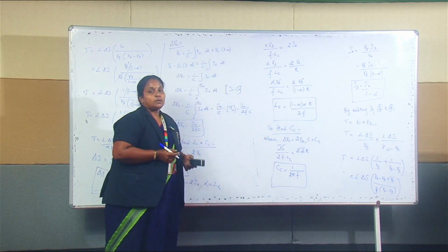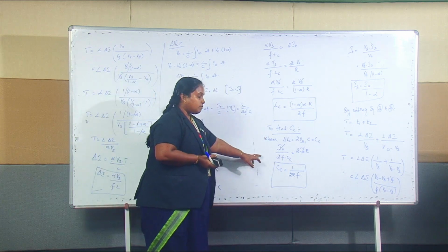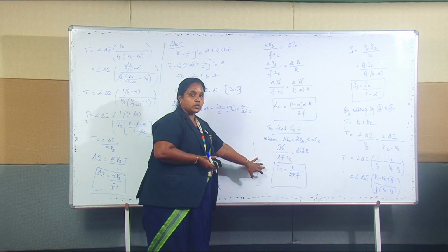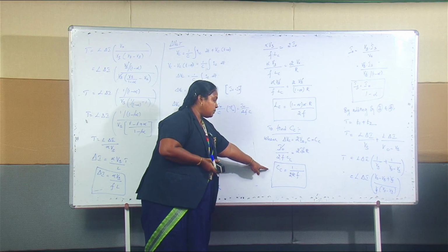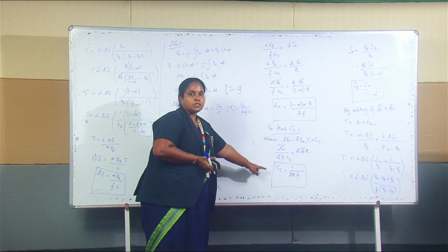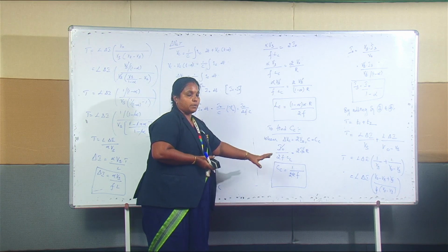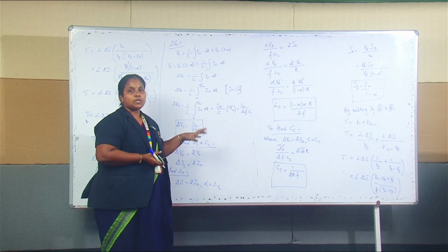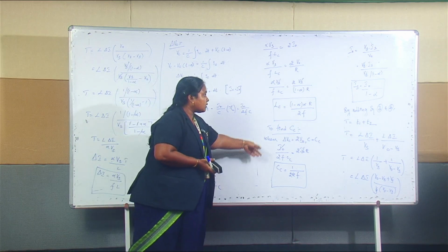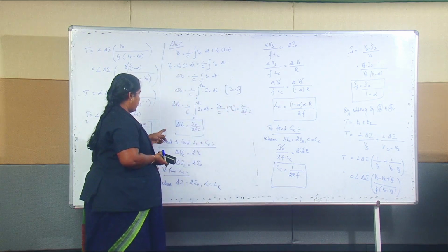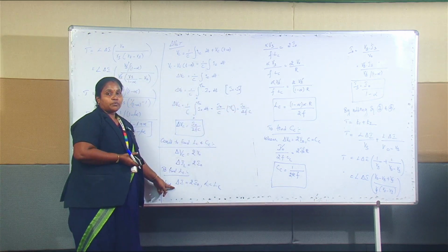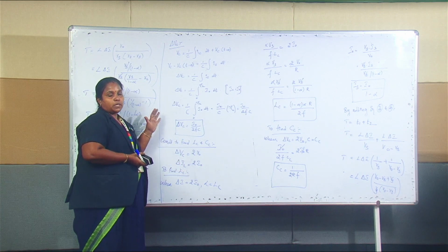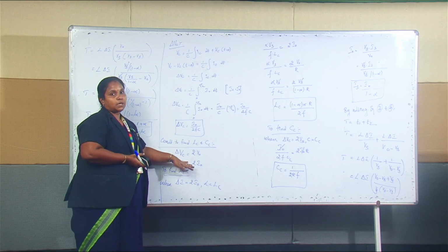So this is the critical value of capacitance. While designing for a high power application, the value of the capacitance should be less than this value. Otherwise, your circuit will be damaged. So these are the expressions which have to be considered while designing your inductor and capacitor, and the standard values of ripple voltage and ripple current have to be considered while designing this buck regulator and the boost regulator circuit.